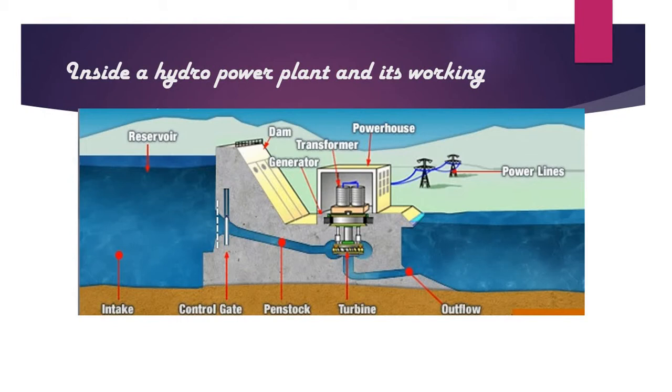The next one is the penstock. Penstock is a pipe between the surge tank and the prime mover or turbine. The structural design of the penstock is the same as for any other pipe, except it has to bear high pressure on the inside surface during sudden decrease and increase in the load. Penstocks are made of steel or reinforced concrete.